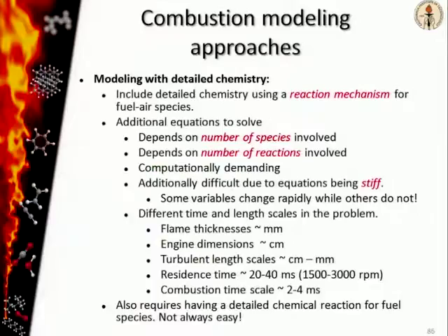Now, the more complicated way to do it is to actually include the full chemistry of the fuel-air mixture. In this case, you have to include detailed chemistry by using a reaction mechanism for the fuel-air species, which includes all the reactions and all the species that can be formed during the combustion process of the fuel with oxygen.